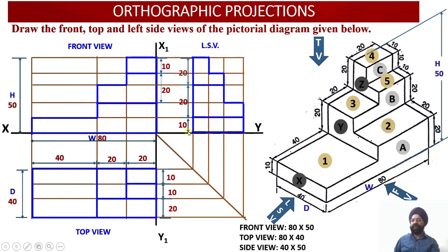So I can remove some of these dimensions because if I add all the three dimensions over here and this total is also mentioned, this will lead to redundancy. So that is why one dimension I have eliminated from here and another one also from here. Please check. Total depth was 40. Here I had mentioned 10 plus 10 plus 20.